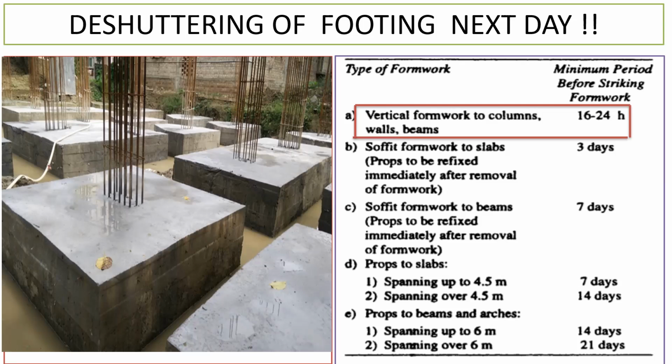So already the water is present in this concrete. So if you don't keep this surface moist, what will happen? Because of the sunlight, whatever water is present in this concrete, that is going to get evaporated. If that gets evaporated, the main idea of putting the water was to help the process of the hydration, to help the process of this concrete, right? To gain the strength, we had put the water. If you don't do the curing of the concrete, the atmosphere, because of the sunlight, whatever water is present in this concrete is going to get evaporated, and whatever strength we want, that is not going to achieve.